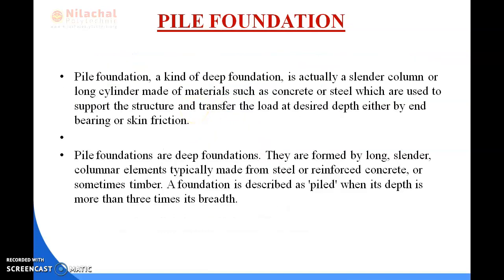Next come to pile foundation. Okay. So under deep foundation, what is deep foundation? It is one in which the depth of the foundation is very large in comparison to others, and which is not constructed by ordinary methods of open pit excavation. Okay, and when is deep foundation used? In cases where a stratum of good bearing capacity is not available near the ground, or space is restricted and does not allow for a spread footing.